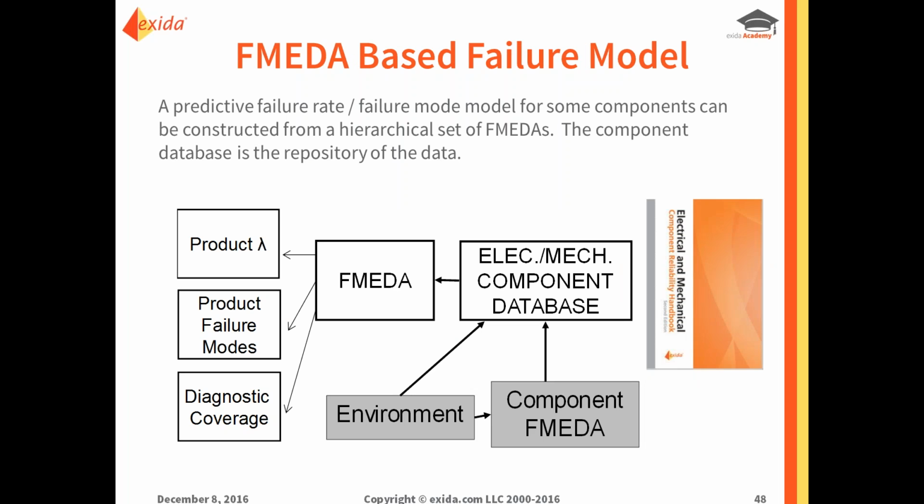Another way to get failure rates is FMEDA, or Failure Modes Effect and Diagnostic Analysis. This is a predictive failure rate analysis. When we do our FMEDAs, we consider the drawing, the bill of material, the environment, and the type of application that this device is going in. So we can look at a subsea valve close-on trip application.